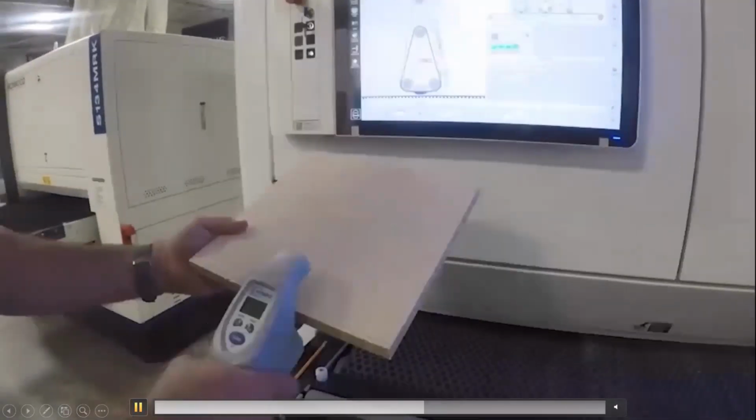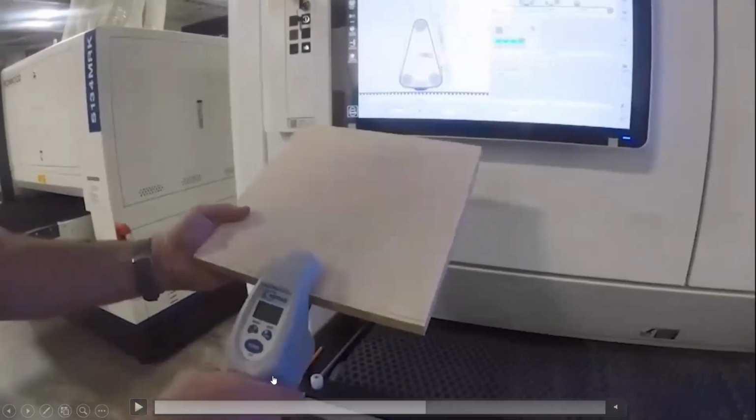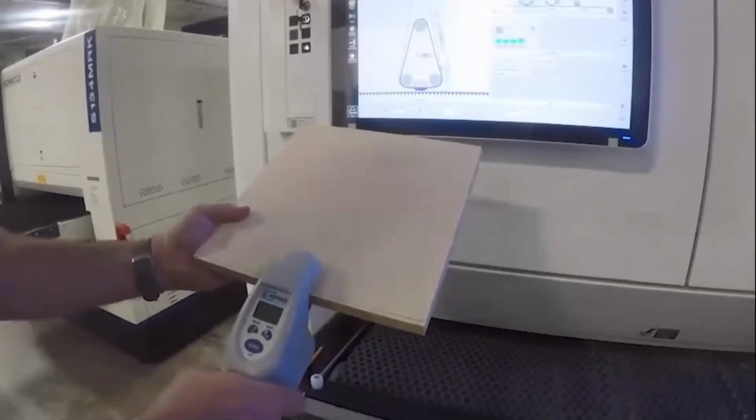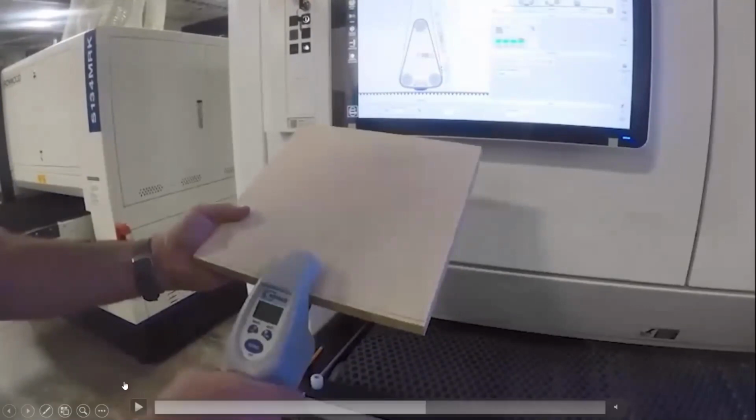Now we're going to measure that workpiece, and you can see here we have a wireless caliper, Bluetooth. It's a nice feature that we have on the Homag sanders where we can measure a workpiece and send that right to the controller. One of the most common issues with sanding is often we're either trying to remove too much or too little material, and oftentimes that can happen based on the thickness.